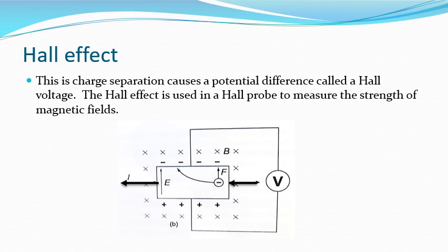Now, if you place it within particular things, so a solenoid, a coil of wire, you get a uniform field relating to the current, so you can calibrate the voltage that you measure in millivolts to the field strength that you're expected to get, and then you can measure it in an unknown situation.